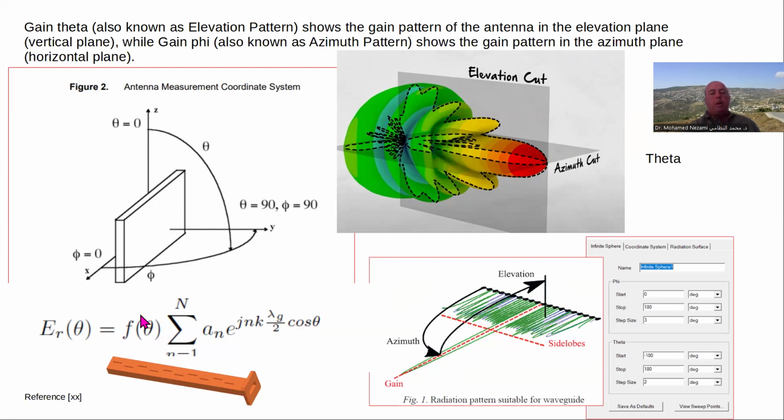So you can see that the radiation pattern from a single slot multiplied by this twiddle factor in here will determine the radiation pattern of this, okay? And so in HFSS, what we do, we fix the phi and theta like this to monitor the azimuth and elevation pattern. So the meaning of what's meant by theta and phi is explained in here.